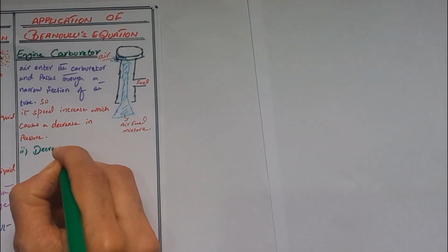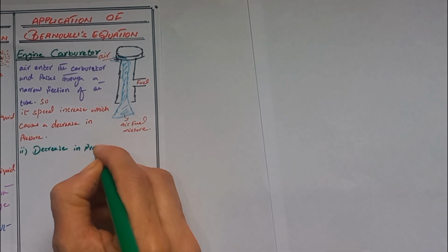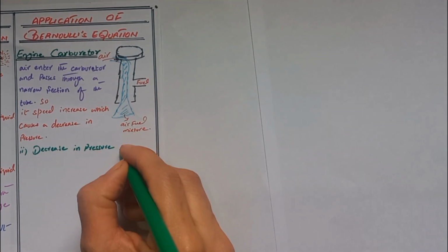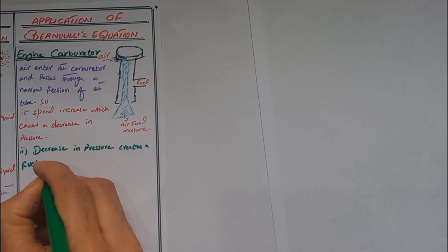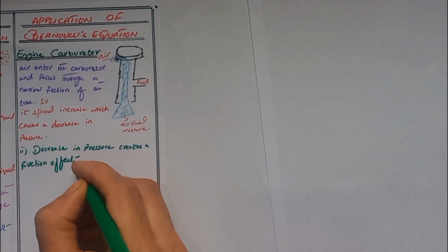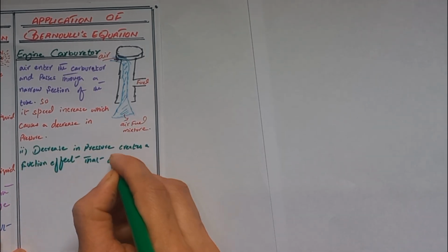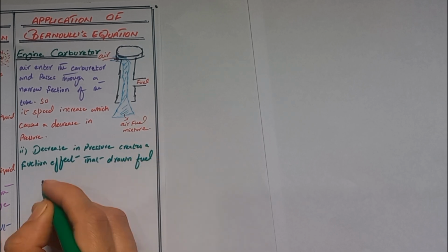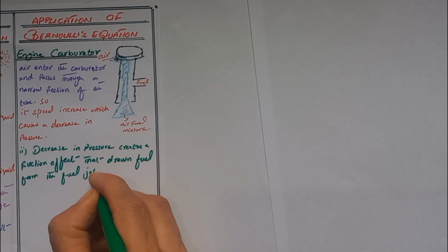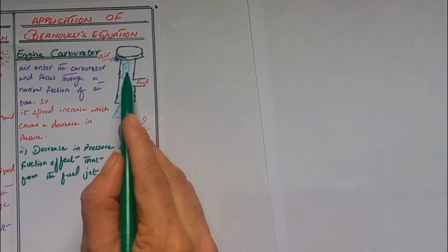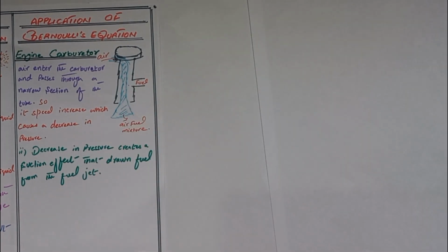The decrease in pressure creates a suction effect that draws fuel from the fuel jet. Here the pressure decreases, which sucks the fuel from the fuel jet.